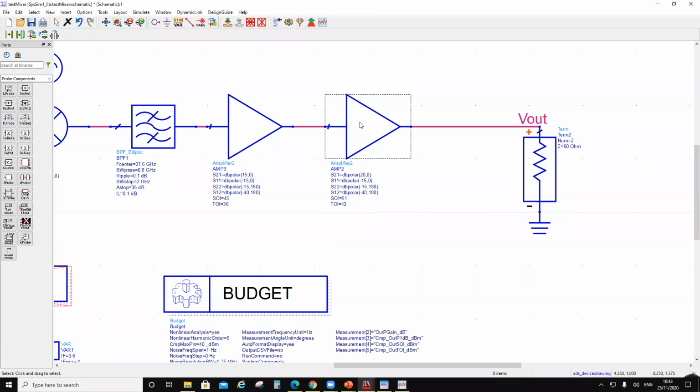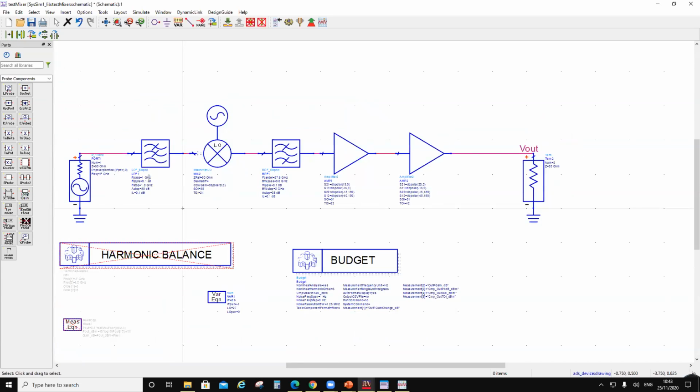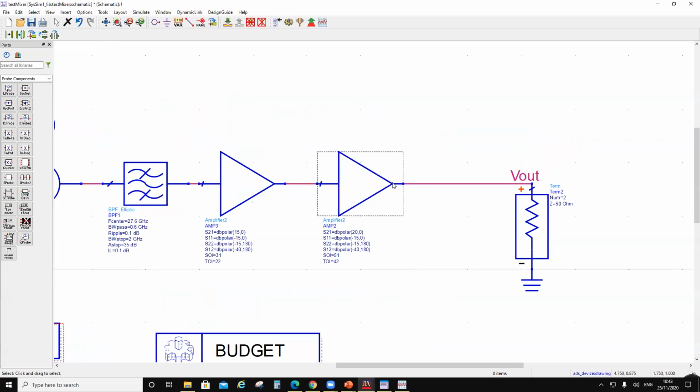So now it will deliver 30 dBm. Then this has a gain of 20, right? So you just bring these numbers down by 20. So if this is 42, then minus 20 will be 22 over here. And this 51, 20 down will be 31 over here. So now what can this one do? This one can deliver 10 dBm. And then a gain of 20 on it. So this one will deliver 30. So that's how you build the chain for a transmitter. Not from the input side. I started the wrong way. Start from the output side, the output power delivered, right?